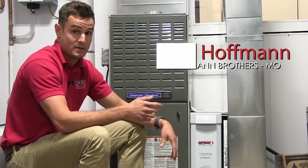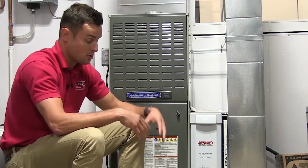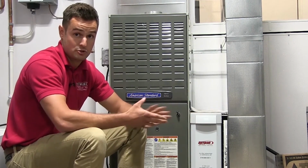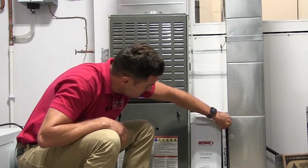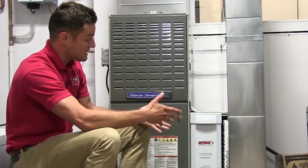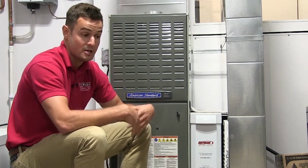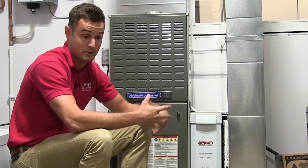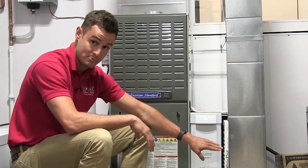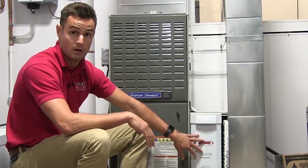So one of the things that we use this particular demonstration and setup for in our training room is to show our technicians, really to make them believe, hey, this is the difference in the static pressure drop between your standard 1-inch filter here and your media cabinet. So we can actually take one or the other out and measure the static pressure differences across the 1-inch versus our 4-inch media cabinet to really get our technicians to believe and say, wow, and you can actually hear the difference in the fan when you have the 4-inch media in versus the 1-inch media. So it really builds belief in our technicians that this is good for our customers.